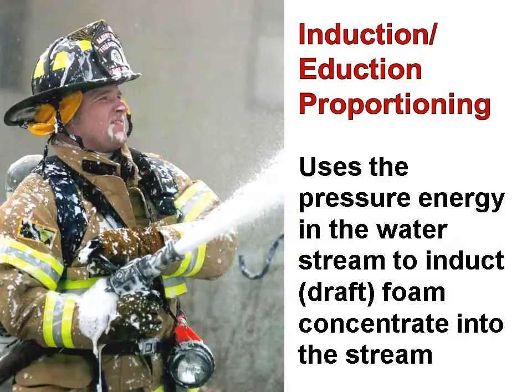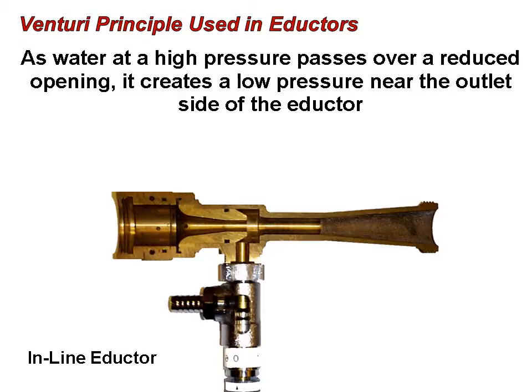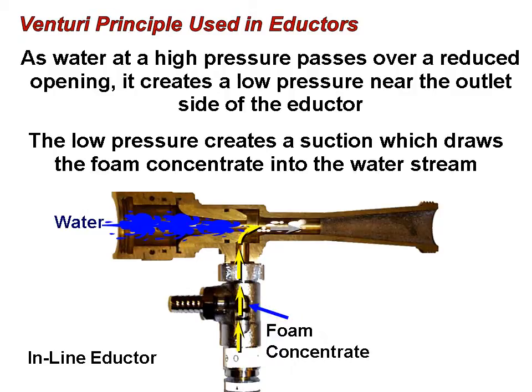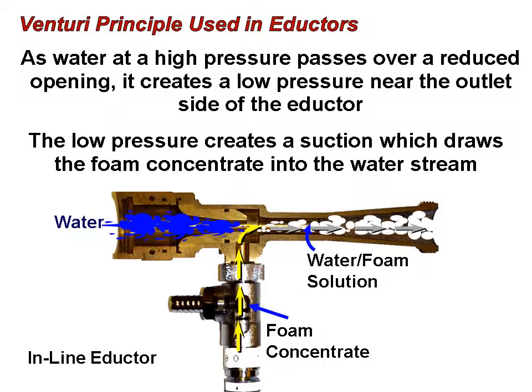Some proportioners use the pressure energy in the water stream to draft concentrate into the foam stream, which is the induction or inducting system. The Venturi principle is used in the inductors. As water at high pressure passes over a reduced opening, it creates a low pressure on the outlet side of the inductor, and it brings the foam up out of your bucket. As you can see there, it makes your foam solution, mixes it there.